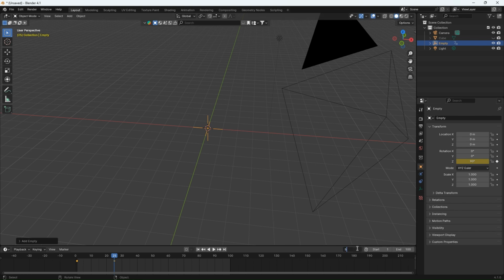Then I'm switching to keyframe 50. Here the value should be 180 degrees, and I select the key. Next keyframe is for 75. I will lock the key. Angle is 270 degrees, and I'll lock the key. The last frame is for 100, and the angle value is 360. I'll lock the key. So let's verify once again.